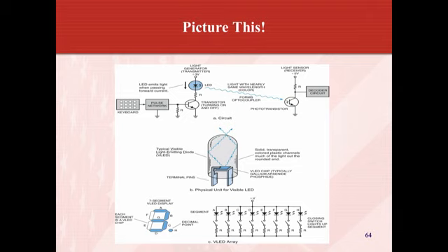They're also showing you the LED giving off light, and they're drawing that squiggly blue line over to what they call a phototransistor, which, if you notice, has no base. The other transistor has a base coming in as the input. The input in this case is the LED giving off the light. That biases that transistor and puts 5 volts through it, and then they're sending the output to a decoder circuit.